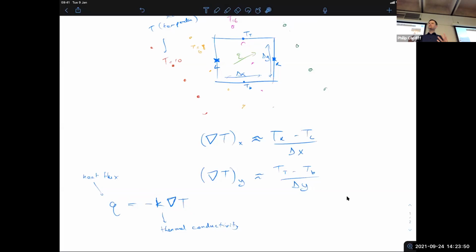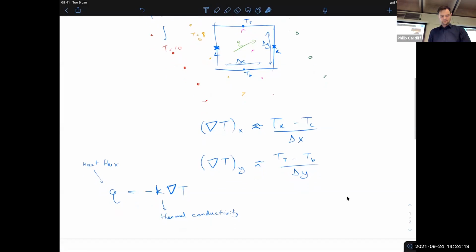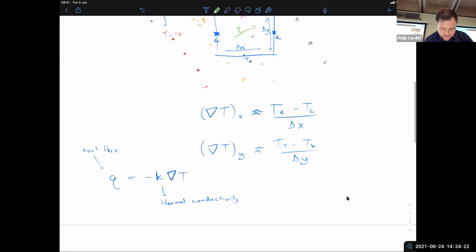It's easier to understand the gradient operator, I guess, thinking about a temperature or something like that, a scalar. And when you think of the gradient of a vector, maybe it's more confusing, but just think of it in terms of its components independently. The x velocity is just a scalar that may increase in one direction, but at the same time, the y component may increase. So the x component of velocity can change in the x, y, and z directions, the same as the y. So that's why you have all these extra numbers. So I could equally draw this image with all these velocity vectors all over the place, and I can get the gradient of velocity as well. Very good. So that's the gradient.